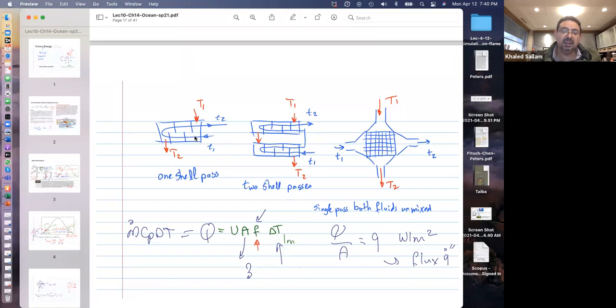But then immediately it's meeting the cold flow inlet, which is the coldest temperature. Why would I put the largest, hottest temperature next to the coldest temperature ever? That changed the delta T between this and this. It's not pure counterflow anymore. And that change in the delta T makes you depend on experiments to come up with a correction factor for it. That's why those charts exist.